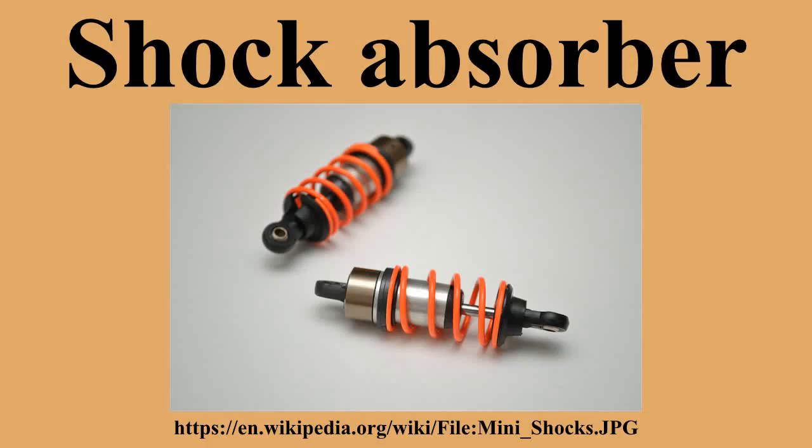be dissipated. Twin-tube gas-charged, variously known as a gas cell two-tube or similarly named design. This variation represented a significant advancement over the basic twin-tube form. Its overall structure is very similar to the twin-tube, but a low-pressure charge of nitrogen gas is added to the reserve tube.